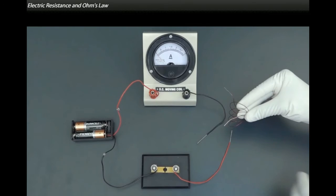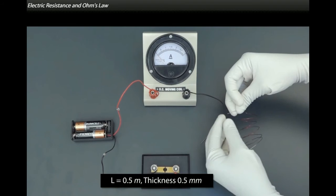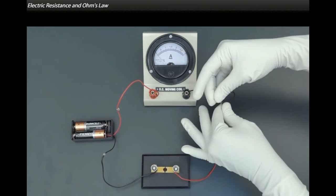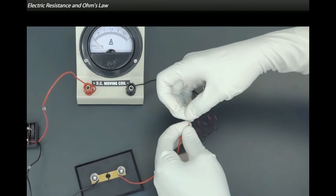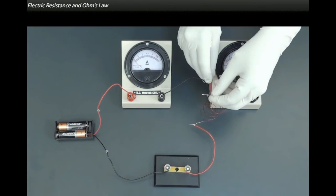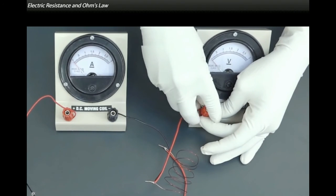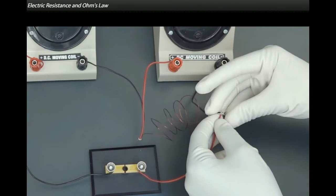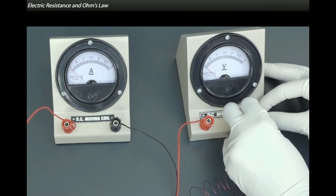Take an insulated copper wire of length 0.5 meters and thickness 0.5 millimeters. Connect it between the two ends P and Q. Connect the end P to the positive terminal of the voltmeter and the end Q to the negative terminal of the voltmeter using connecting wires.